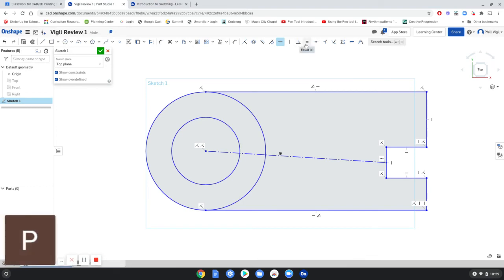So this time, instead of clicking on the constraint tool first, I'm going to pre-select the lines. So I'm going to press Escape to get out of the previous constraint, which I'm still in horizontal. Press Escape. Now I have my select tool. I'm going to select these 3 lines.